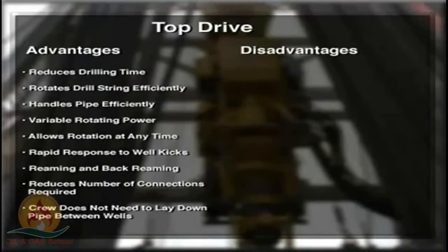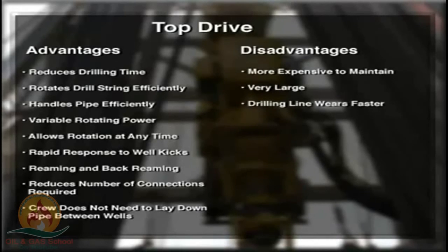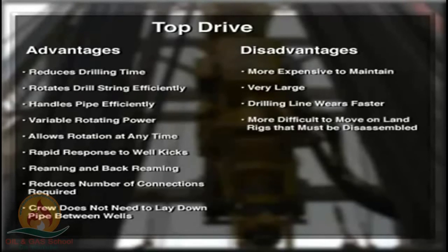Top drives have a few disadvantages. They are more expensive to maintain, and they are very large. Because of the additional weight, the rig's drilling line wears faster. They are more difficult to move on land rigs that must be disassembled.